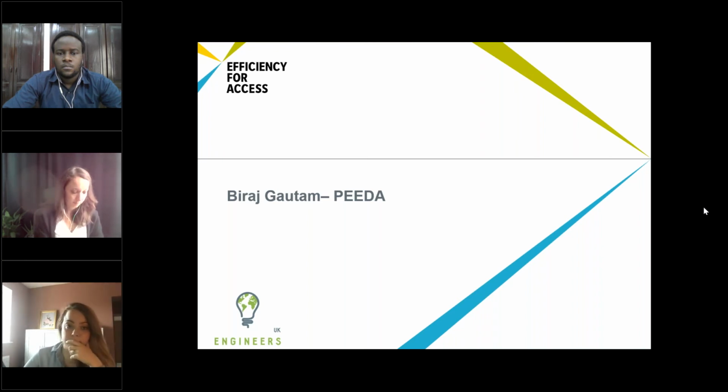I would like to give one example of how we faced difficulties when we did the electric cooking stoves project in the past. In one of our research projects, we did some laboratory research and found that 1 kilowatt capacity was sufficient to cook most Nepalese foods. But the induction cooking stoves that we wanted to use for that research had a 2 kilowatt rating. All of the induction cooking stoves that we find in Kathmandu are in the 1.8 to 2.3 kilowatt range.